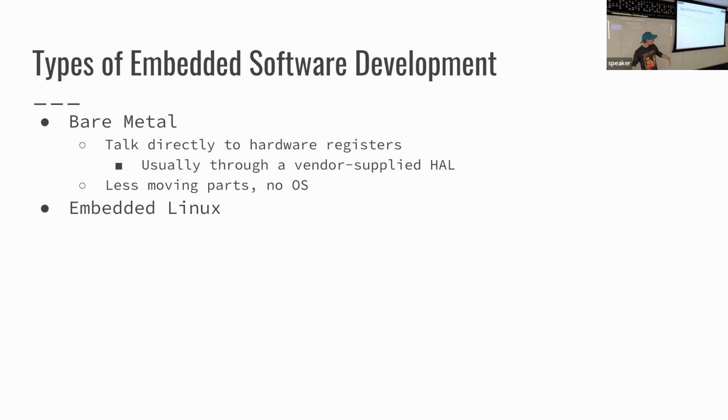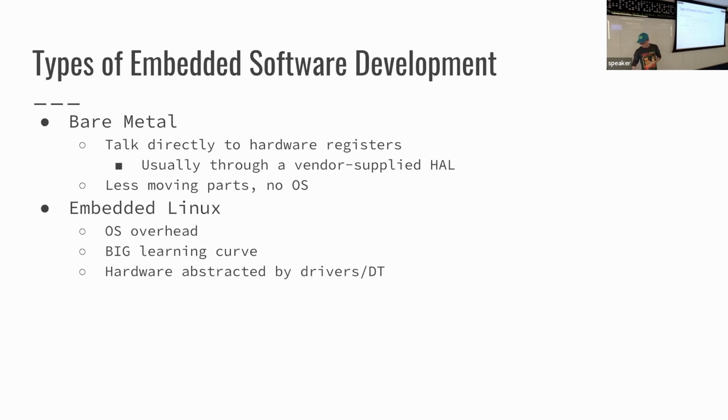On the other end of the spectrum, you'll hear about embedded Linux a lot, which is a really cool way to develop too. But if you're just starting out with embedded programming, and especially if you haven't learned Linux yet, there's just so much to learn right away. You have to either roll your own Linux or use a build system like Buildroot or Yocto and package your application with it, deploy it to a board, and on top of that, know all the bare metal stuff as well. So it's not a horrible place to start, but there's just a lot more to do and fussing around.